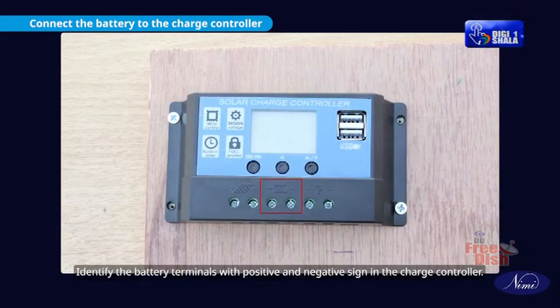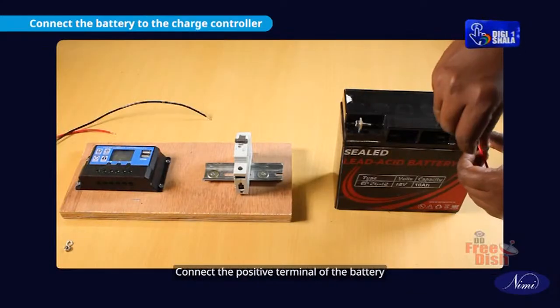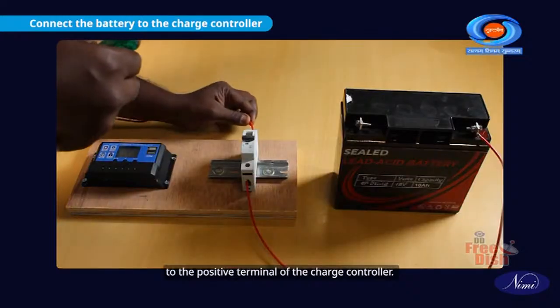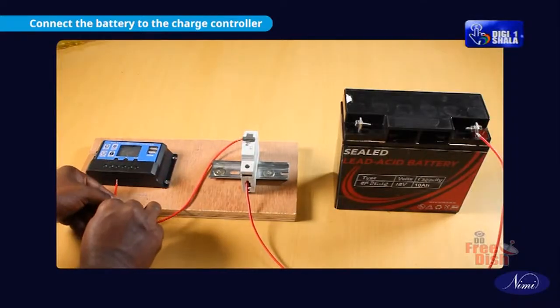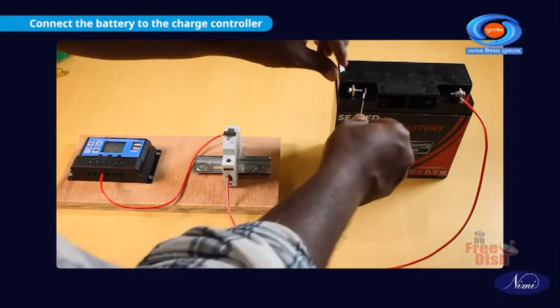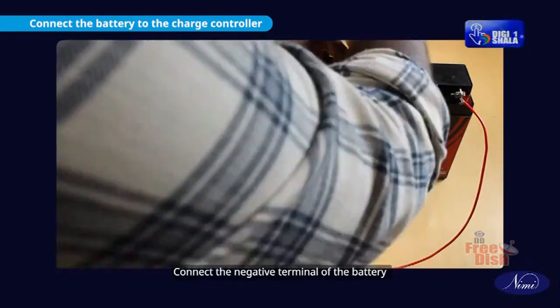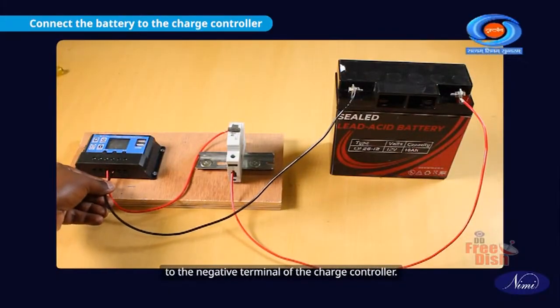Identify the battery terminals with positive and negative signs in the charge controller. The charge controller typically has labeled terminals for connection. Connect the positive terminal of the battery to the positive terminal of the charge controller. Connect the negative terminal of the battery to the negative terminal of the charge controller.